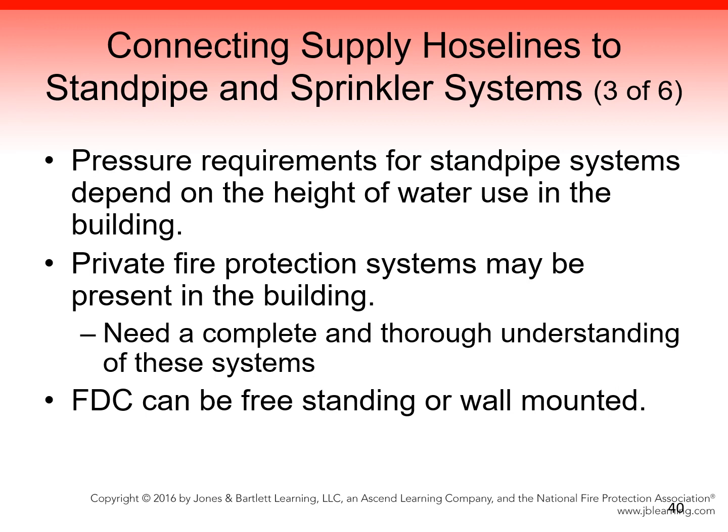When performing this planning or during routine driving through your response area, you should be looking for the FDCs, hydrant locations and sprinkler valves associated with the building. If you are unaware of the locations or cannot find the FDC connection on the scene, you become the owner of the problem, with all eyes looking at you for its resolution.